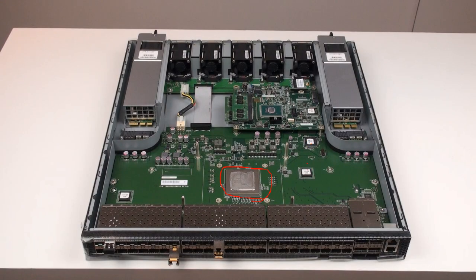These are all the other CPLDs which are managing things. They can manage the SFPs here. They can read and write. They can read the SFP information on the front ports, or manage the LEDs. It has all of these LEDs in the front, and the CPLDs manage them, along with other functions of the switch. Here we also got management ports and a console port. So this particular chipset, you see here, is a small PHY for that management interface, and that serial connection is also routed all the way back to the CPU.